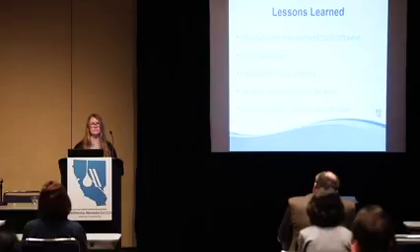Another side note, one thing we felt was really important is that even though the MCL is 5 PPT, we can ask for our analytical data from the lab and see numbers less than 5 PPT that are statistically relevant. We know there's something there. So that's one thing we've really started focusing on too. At each one of these points where we're sampling, we understand we're getting close to 5 PPT, so we don't wait until we're over the MCL or at the MCL. We're able to plan a little bit ahead because we're looking at that data.